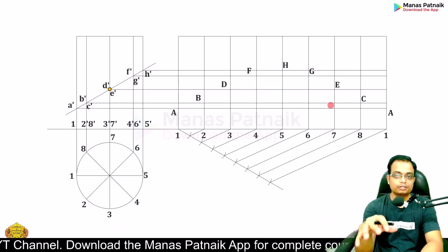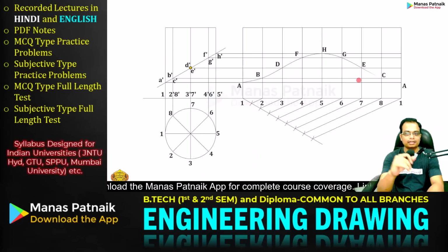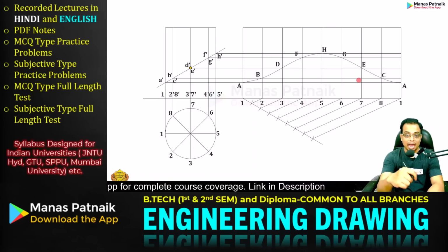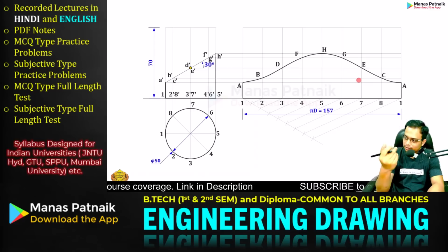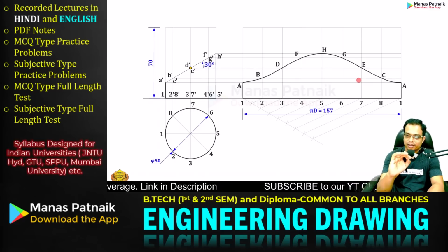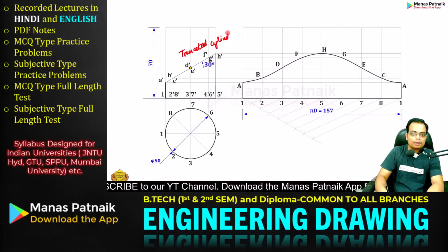And since this is a case of a cylinder, all the points should be joined with the help of a smooth curve like this. And if you want to see the dimensioning, the construction work, how light it should be, and the outlines, how bold they should be, it would look like this. This is the final work. Development of surface of a hollow truncated cylinder. This is the truncated cylinder. Okay, I hope that I have made myself absolutely clear.